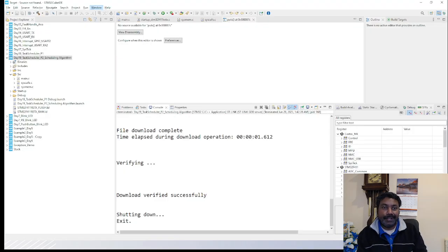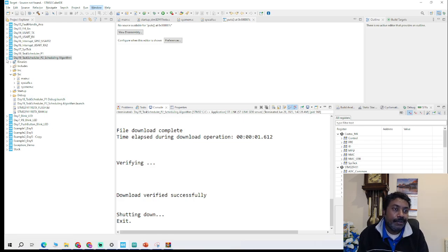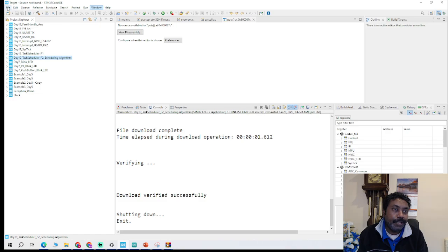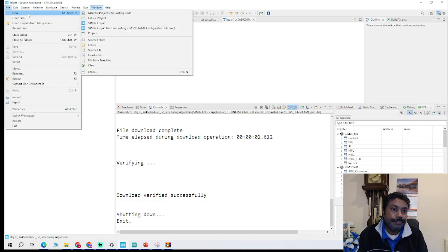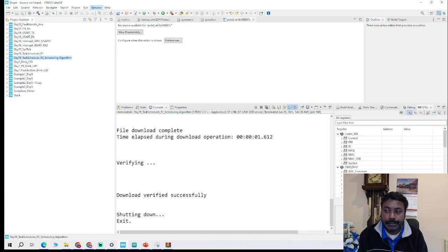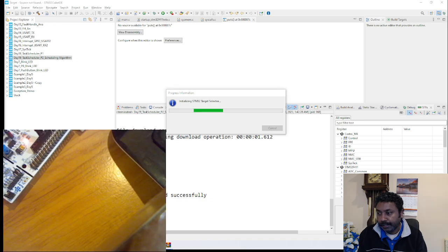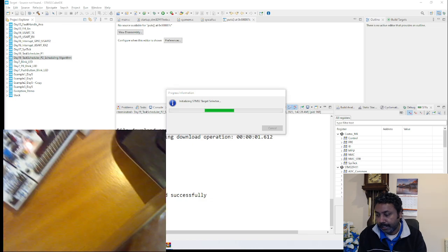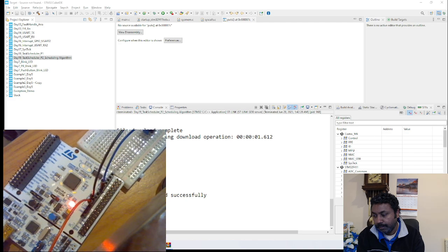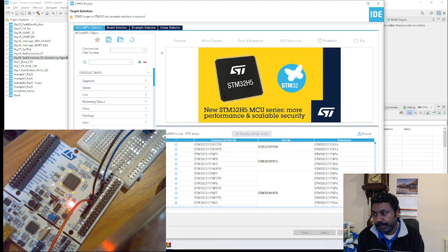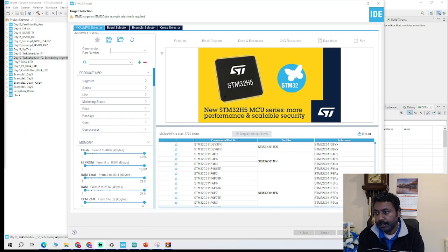So, for our convenience, I already opened the IDE. We're going to start a new program. I'm going to go File, New Project, New STM32 project, and it will let you select the target selector. I have also connected the hardware, as you can see, with the breadboard. You need to connect the hardware as well. I'll take this view off now, I'll show you later.